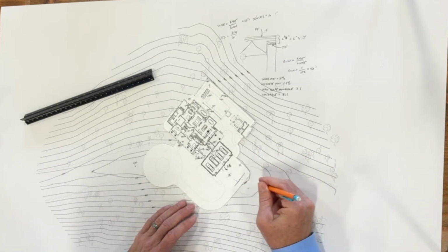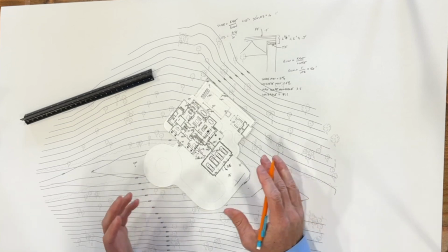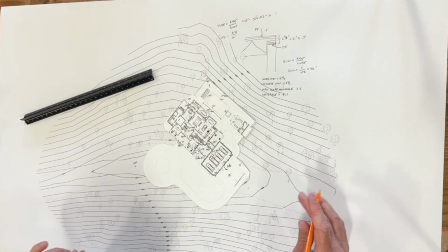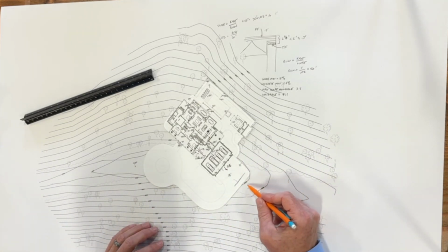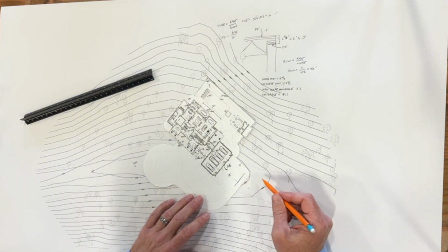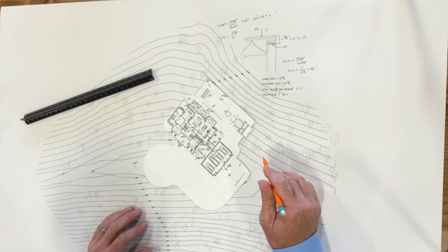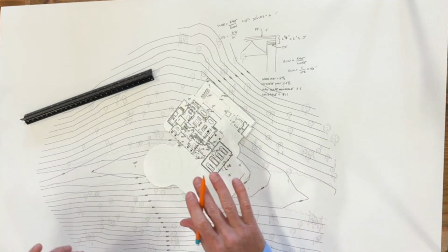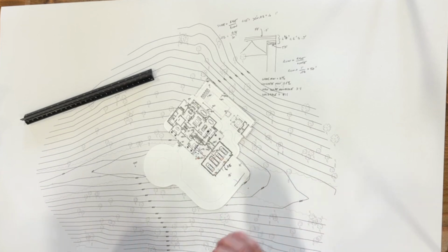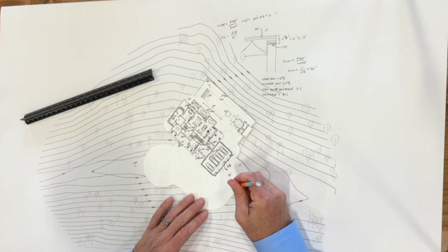Now we'll see what happens over here to see if that makes sense, or if where I get just so far off the hill or something, it just seems dumb. But I can already see this contour is a 339, or is that a 6? 336. So it's like 4 feet above. We'll see if we got to chase that too far. You'll see what I mean by chasing contours, like how that happens. But for now, we'll just put that right there.